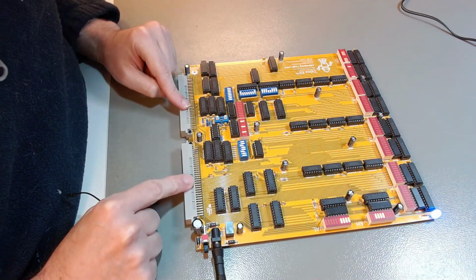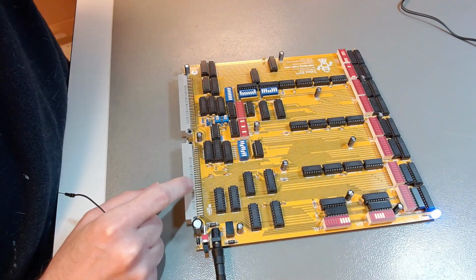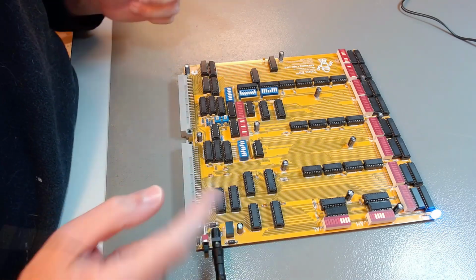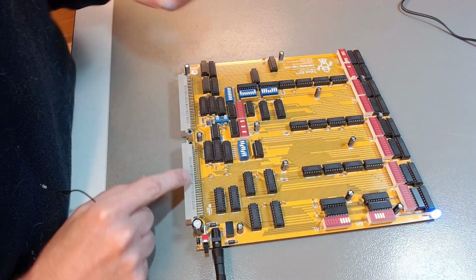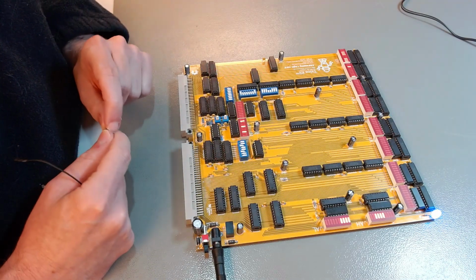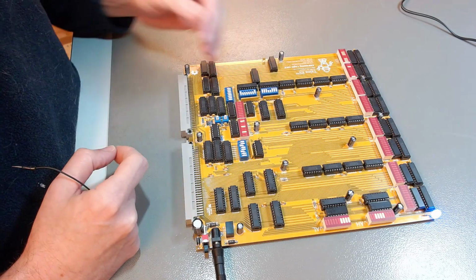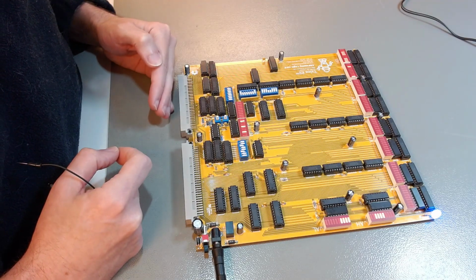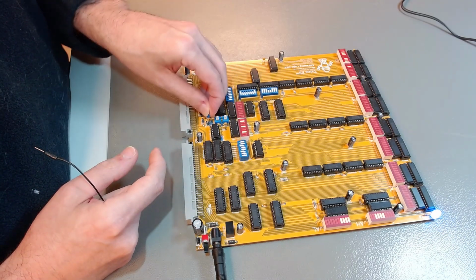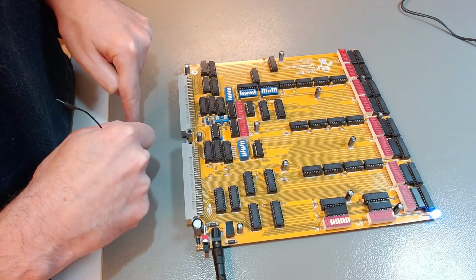We can test the output enables with a multimeter. I did test it and I can tell you it's working, but it's not going to be interesting to show it to you, because I just put the multimeter here to see when the pins float and when they are being driven, and that's correct. What we can do is put this shunt across this header, and then the board will be in standalone mode, which means that the internal bus will not be driven by the dip switches. It will be driven from the backplane connector, which is not connected, so the bus will float. Let's see. And indeed it floats. Even the control signals, which now come from the outside, are floating.